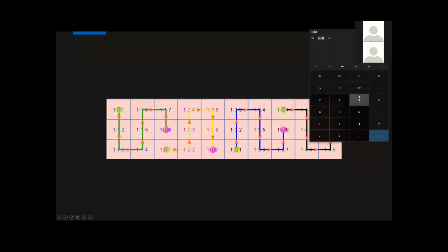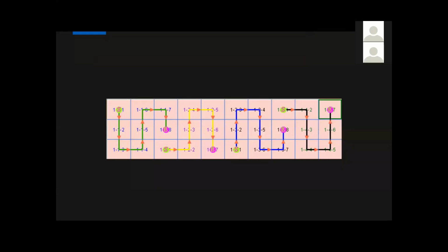For the whole screen, which is 1920 by 1152, the total is within 2.3 million pixels. So theoretically, the 660 has a 2.3 million pixel load capacity, and each port can control 8 panels. That's the information we know by calculation. One of our clients' engineers made this screen connection: port 1 has 8 panels, port 2 has 7, port 3 has 8, and port 4 has 7. By calculation, 8 panels is good and the total resolution is within 2.3 million, so it should work with this mapping.